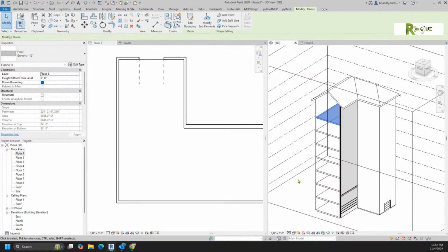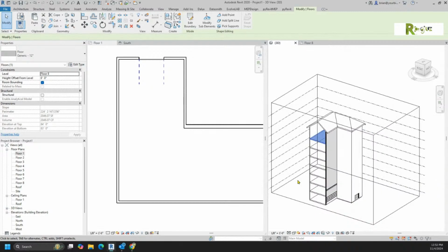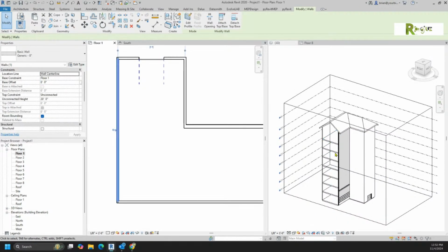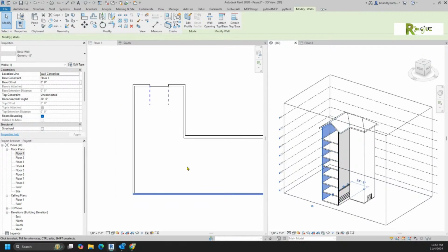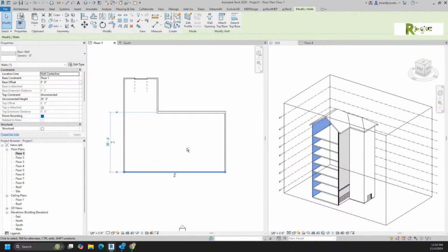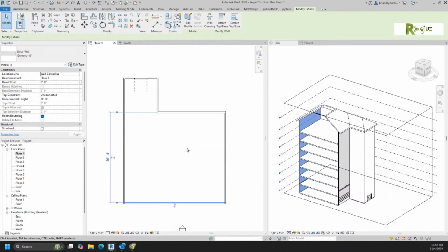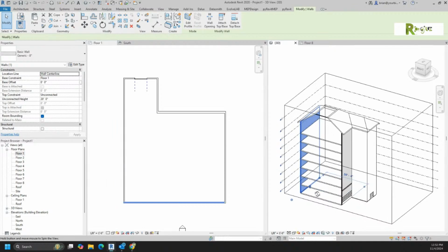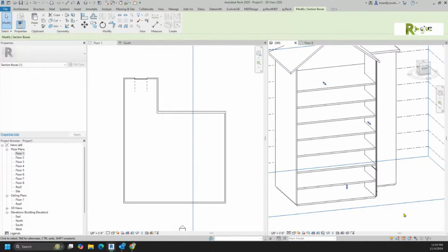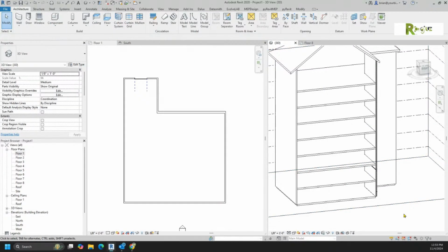Now, if we've worked the way that we just did, the big benefit is if I take this wall and nudge it, you'll notice how all those walls, all those floors, all that stuff is automatically growing. That wouldn't have happened the way you were drawing when we first started. Remember how you showed me how, Brian, I drew a floor and then I went back in and drew the walls? If you draw them out of order, you don't get that relationship.